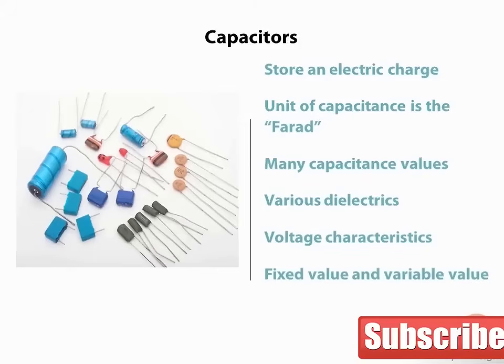Capacitors can have fixed or variable values. We can find variable capacitors such as trim capacitors that can be adjusted with a screwdriver. Older vacuum tube radios have large tuning capacitors with air as the dielectric. These were adjusted to tune the frequency of the receiver. And some transducers will change capacitance proportional to the measured element. Many pressure transducers and touchscreens are capacitive devices. Condenser microphones are essentially a capacitor. Condenser is another word for capacitor.